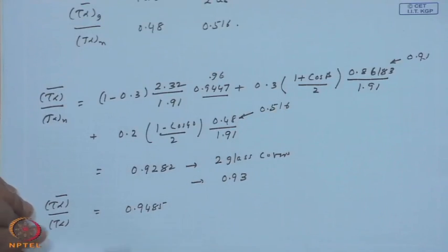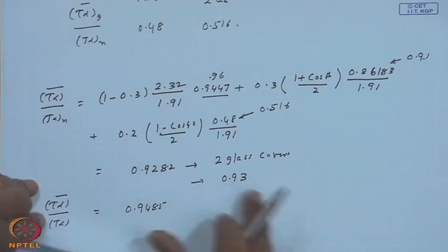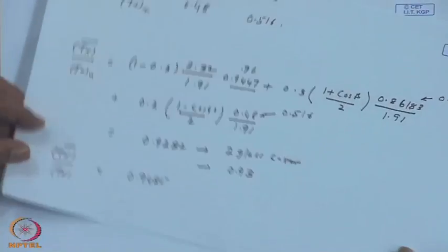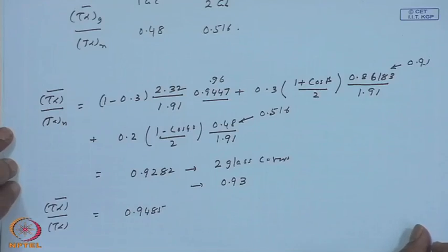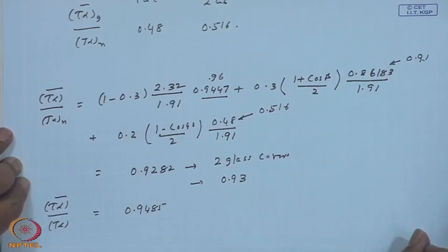So, it will be enhanced. So, the truth may be between 0.95 and 0.93, the average is 0.94. Since we do not have that data, remember we now got the detail of calculating the transmittance-absorptance product or the absorbed radiation for a day.